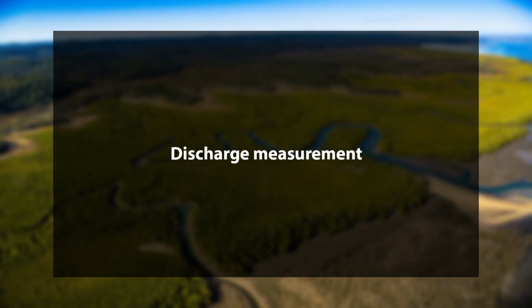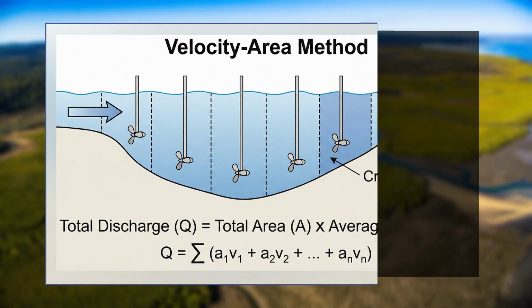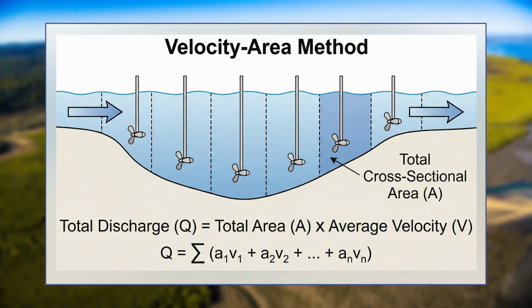Now, discharge measurement. Discharge is the total volume of water that flows through a river. The most widely used method is the velocity area approach. It is based on the fundamental relationship of multiplying the area of river cross section and the velocity of flowing water. Thus, discharge or Q is equal to A multiplied by V.